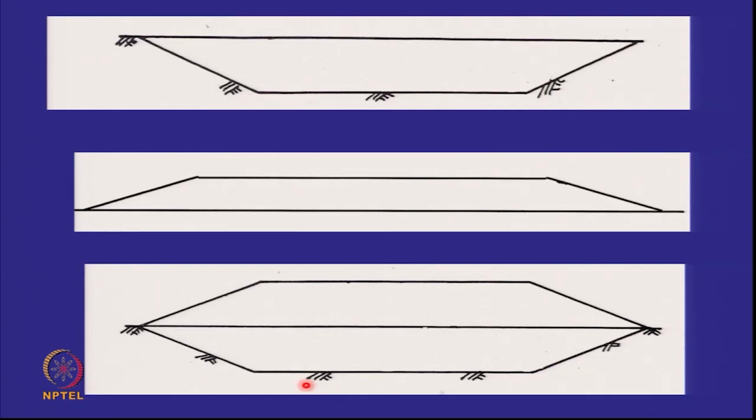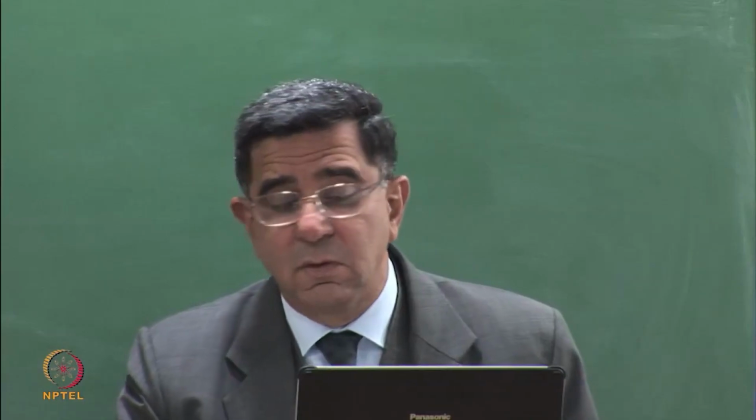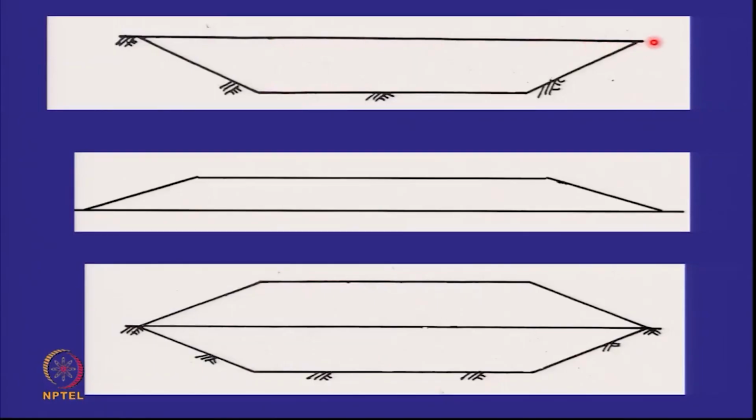The important point I want to make, which I perhaps did not make last time, was that these are vertically exaggerated diagrams. Please understand. This is the width of the landfill, so this can be very large, and this is the depth. This is limited. As I told you, typically this will be 7 to 8 meters in unsupported excavation if the water table is deep below, but this width can be large, and for municipal solid waste landfills it can be several hundred meters, or it can be a kilometer or two. In hazardous waste landfills, which are smaller than municipal solid waste landfills, this dimension can be a few hundred meters.